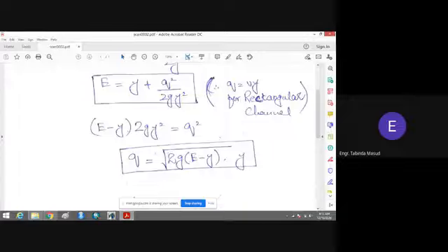So taking the energy as constant, and 2g as a constant term, you can put different values of y in this equation and get different values of the unit discharge, and you can develop a relationship between the unit discharge and the depth of the flow, and then we will construct a discharge curve.